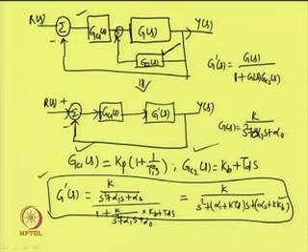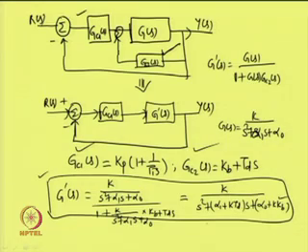Had there been no GC2(s), there is no scope for placing the poles of the original process at desired locations. So, Kb and Td now enable one to locate the poles of the modified process or the original process at suitable locations with the help of GC2(s).